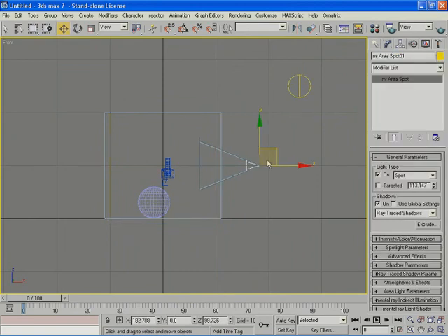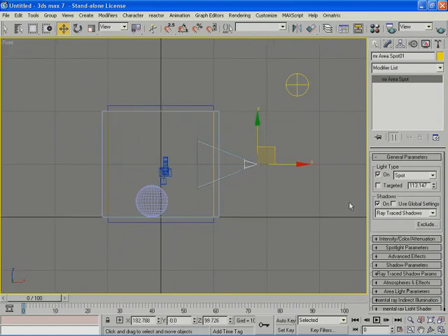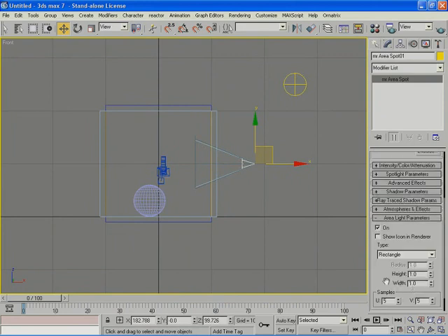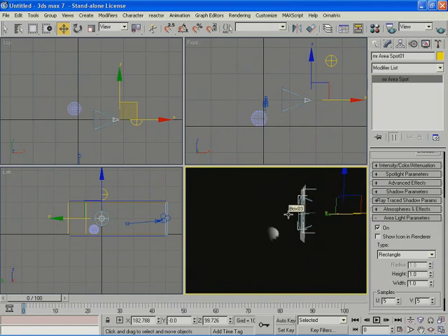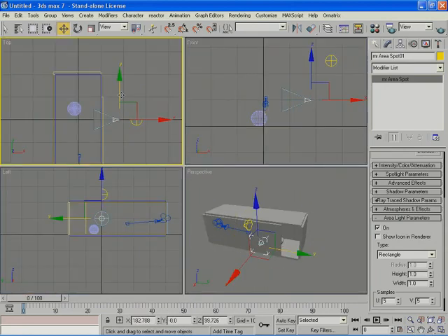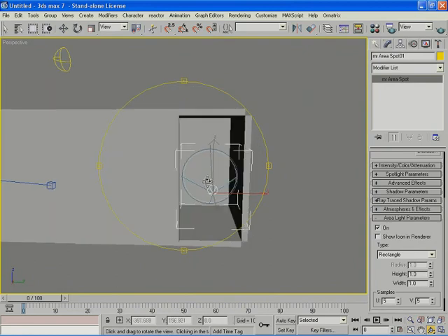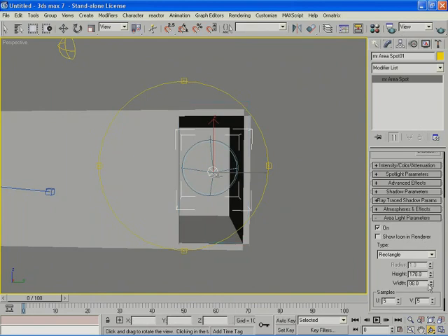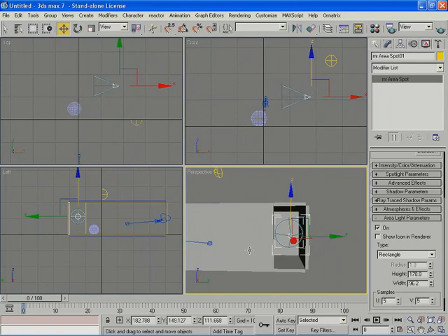Here, I need the dimension. I'm going to press P here and go outside. Press Control L to regain my normal display. I need the dimensions of the area light to be the same as the opening here. So I need to increase the height, and the marker that defines the area light should be approximately the same dimensions as the opening. So I'm going to move this up a little bit and go like this. So now I have an area light that fits the opening, which is what I should have. So every time you have a window and you're rendering with global illumination, you should have an area light that shines through, even though you do have a skylight object. This is a requirement when you work with interior scenes like this.